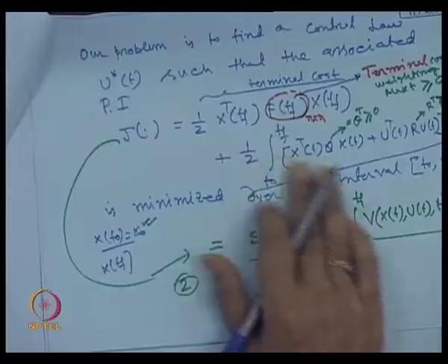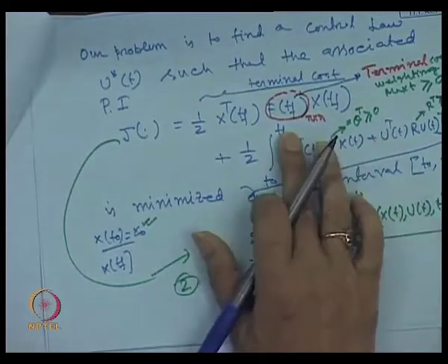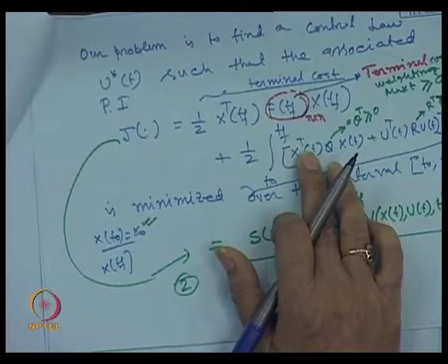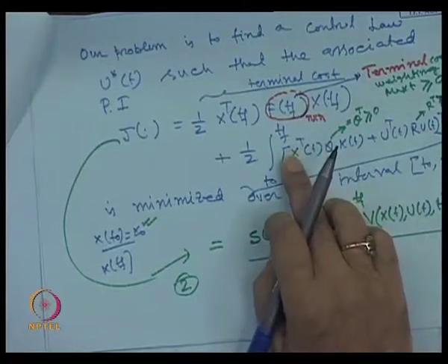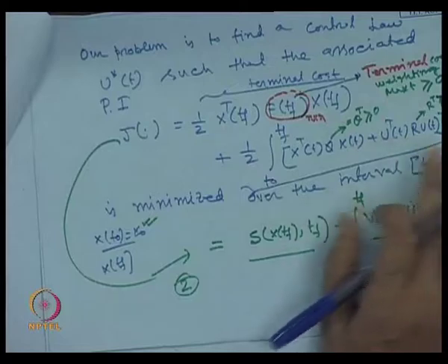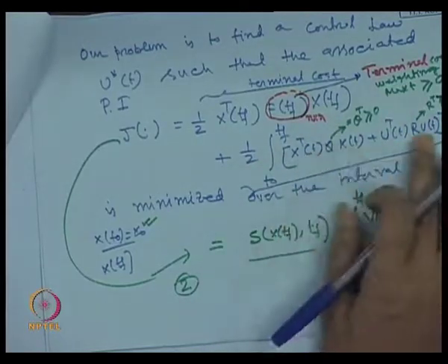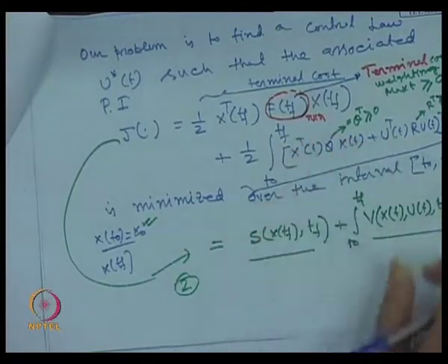The input effort may be extremely high, which we cannot directly apply to the system. Likewise, if you do not consider the state weighting term of the quadratic performance index, then we do not have any control on the state. That is why we take a linear combination of the state weighting and the input weighting, minimizing both the state effort and the control effort.